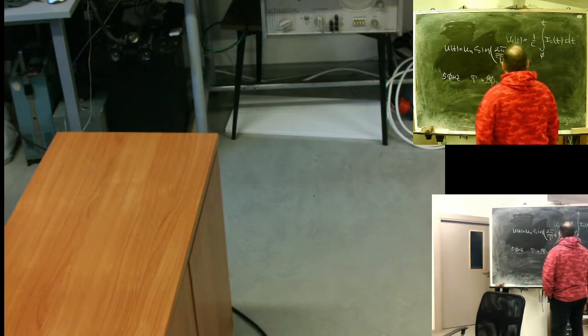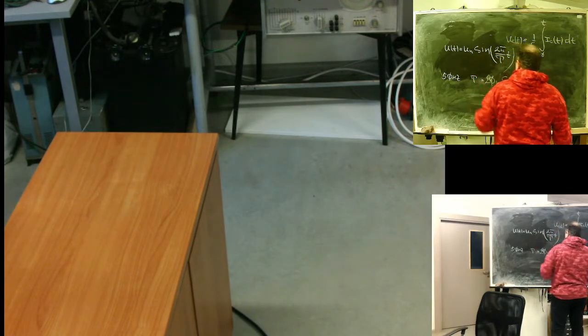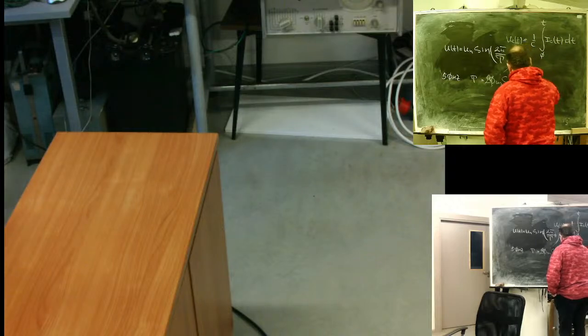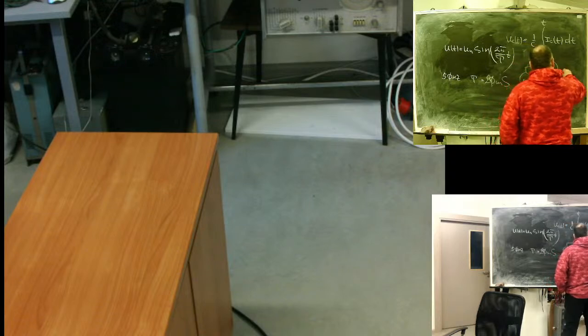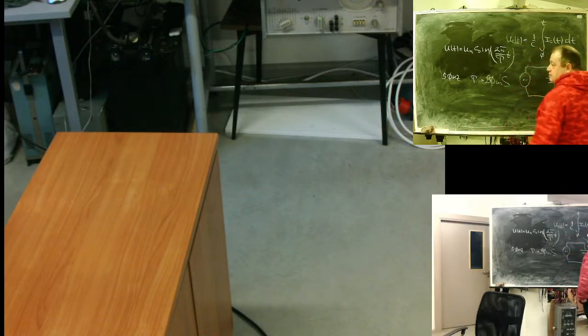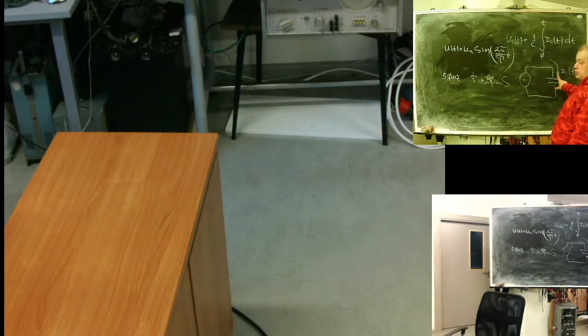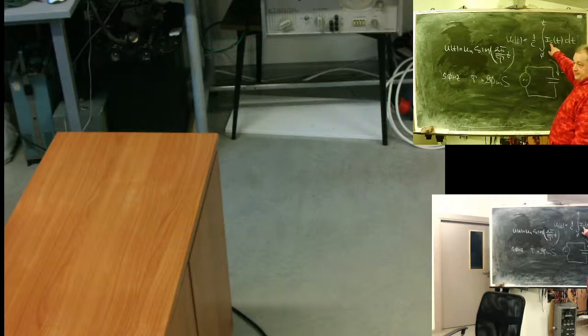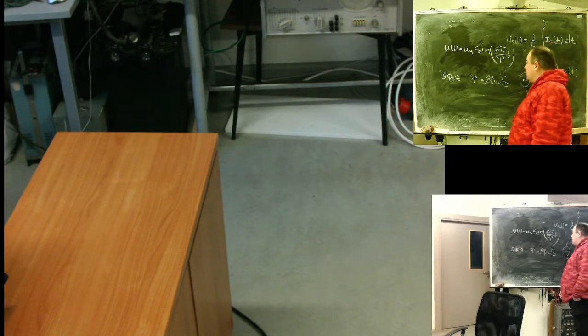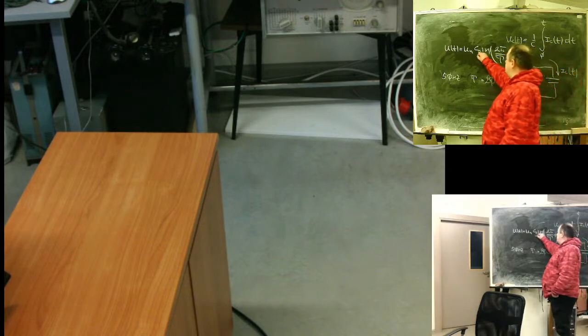What will be our voltage? What do we have? Source, capacitor. The capacitor voltage equals the mains voltage. So what should we do to get current? Take a derivative to get rid of integration. If we take a derivative of the sine, what will we get?